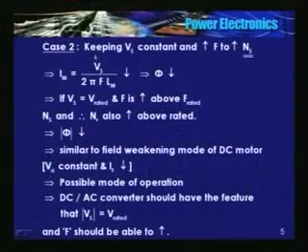What does the equation say? Im is given by Vs divided by 2 pi f into Lm. Vs constant, f increases, therefore Im reduces. If Im reduces, flux also reduces. The relationship between Im and phi will be approximately linear, because beyond the knee point it is non-linear, below the knee point the relationship on the BH curve is almost linear.